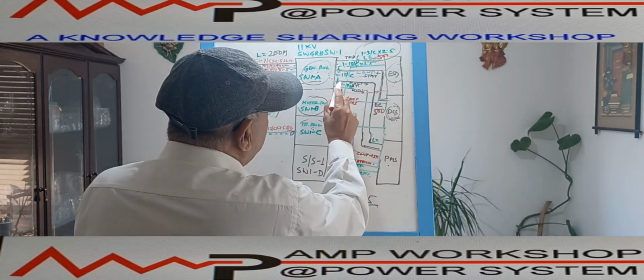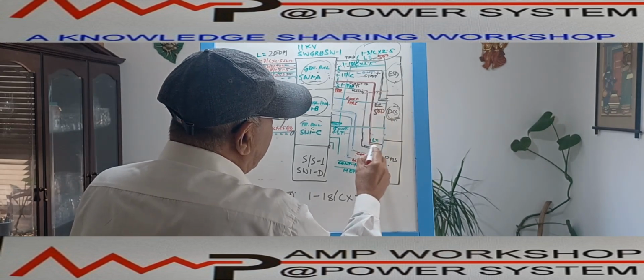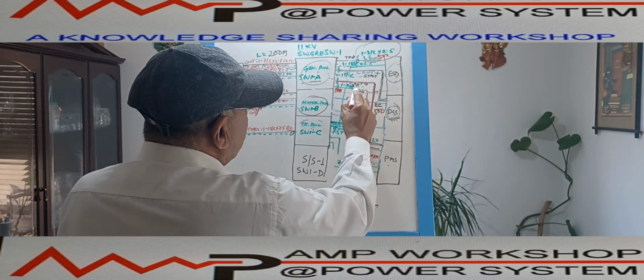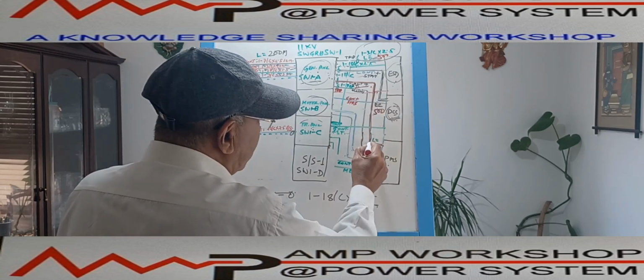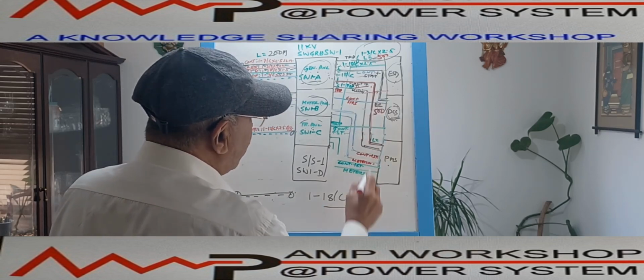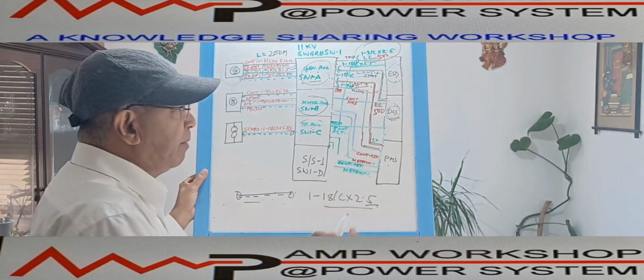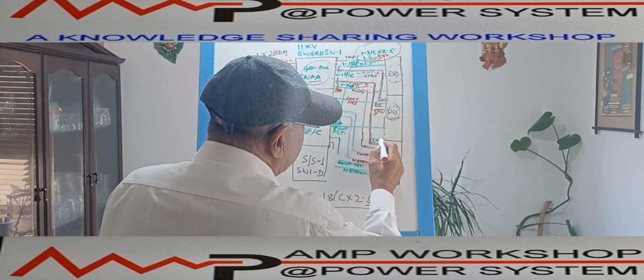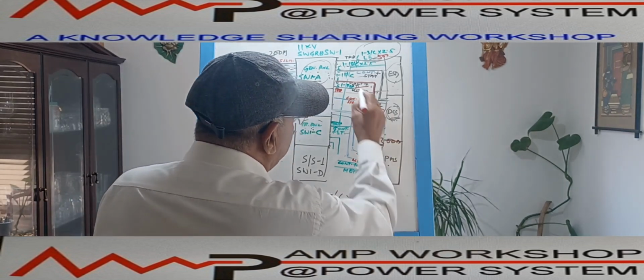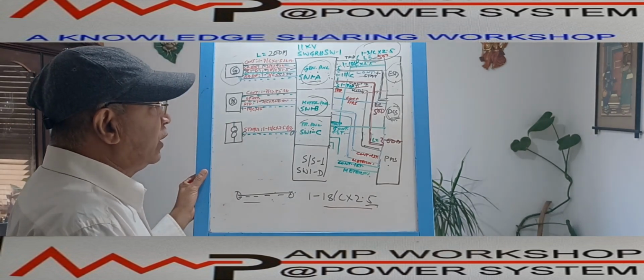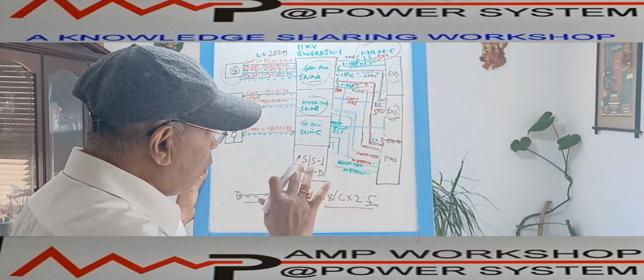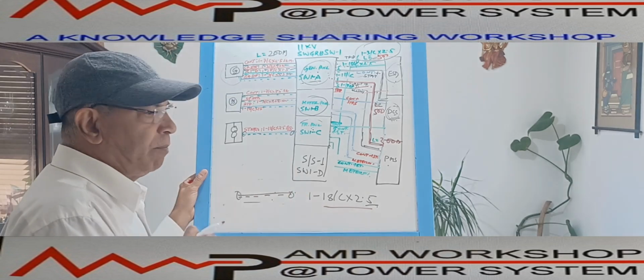You see, this is the control cable, the control and indication cable coming to the PMS panel. That is for control and status. It is an 18-core cable, the same 18-core 2.5 square millimeter cable, and this PMS may be located in a separate PMS room. Suppose this length is 300 meters. So we write down over here 300 meter. So these are the control and indication, and tripping point of view.